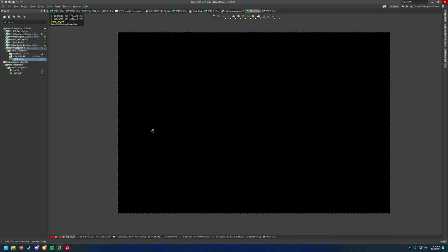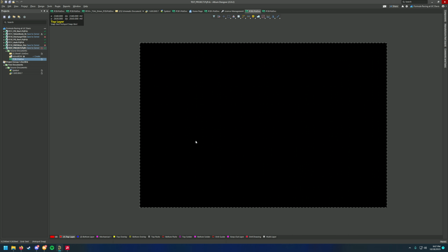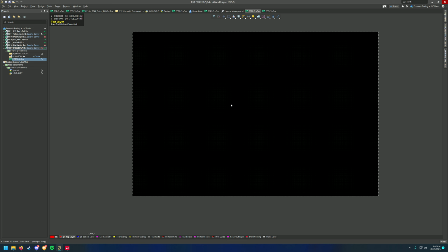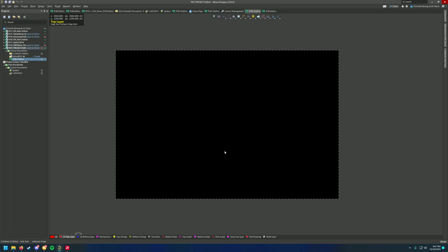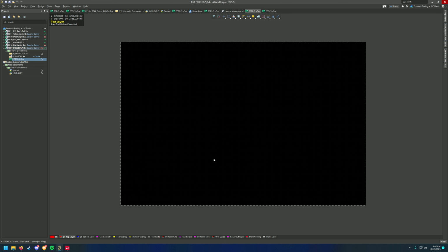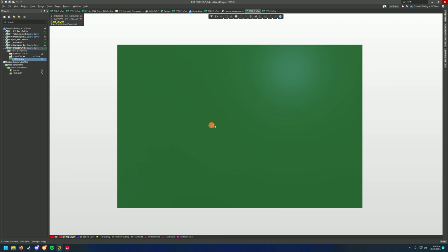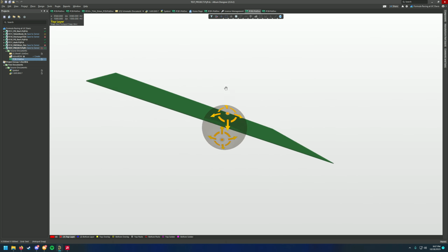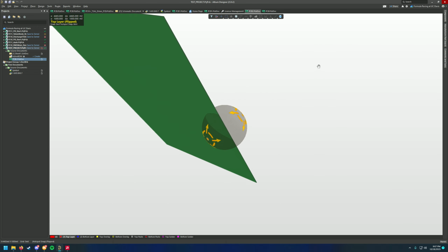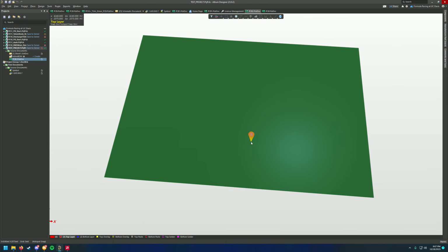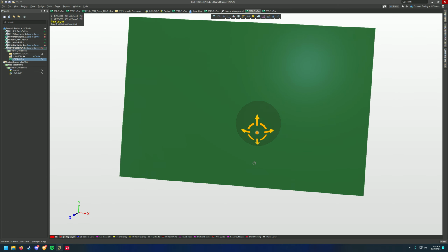So before we get too deep into it, let me go back to the idea. So there's a few different ways you can look at the PCB. So this is two-dimensional mode. So this is where you'll want to be when you're making changes. But then there's also three-dimensional mode, which is nice for just looking how it's actually going to look physically. So if you hit 3 on the keyboard for 3D, then you'll have, right now it's not very exciting because there's not much on here. And so 2 for 2D mode, 3 for 3D mode.